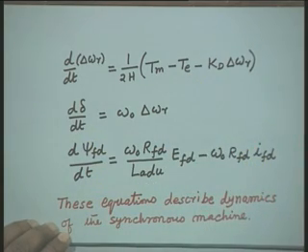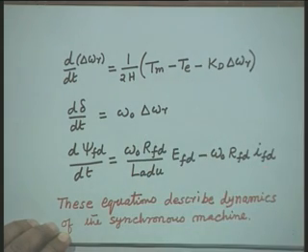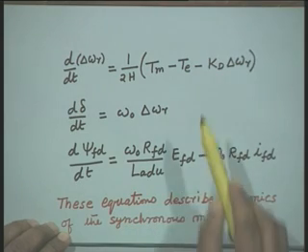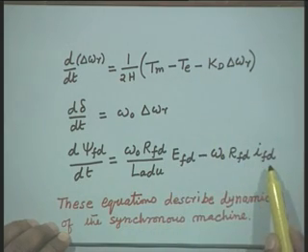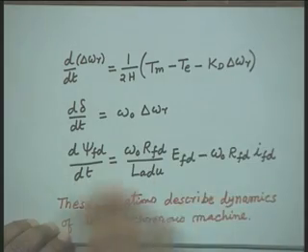Te and Ifd are not state variables, nor are they input quantities, and therefore there is a necessity to express these 2 quantities, Te and Ifd, in terms of state variables. The moment we succeed in expressing the air gap torque and the field current in terms of state variables, we can write down the complete model of the system, as far as these equations are concerned.